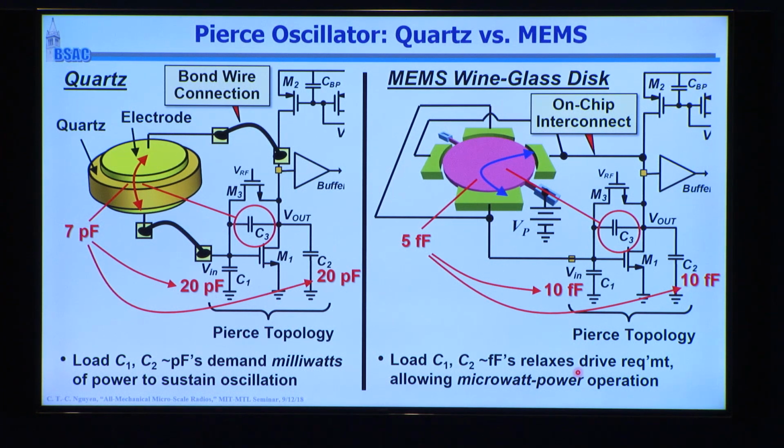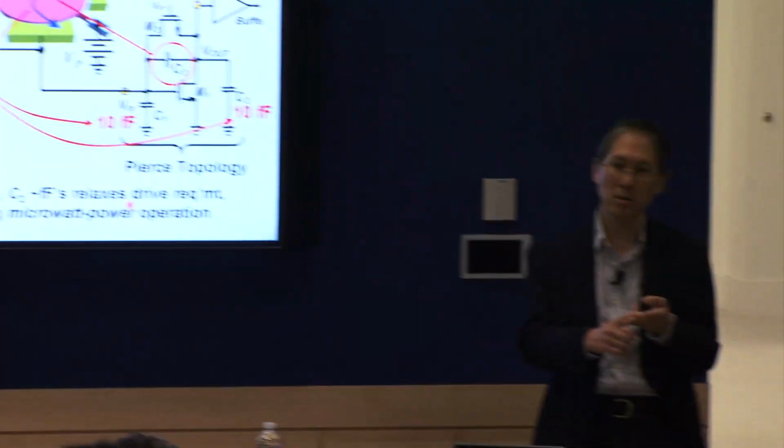The other MEMS advantages are they're actually more stable because of the way they're manufactured, at least by SiTime, is so clean that their aging rate is better than quartz now. And in addition, they actually can get the thermal stability better than quartz. So everything with MEMS now is better than quartz. It's just a technology that's taking time to gain market share, but they are gaining market.